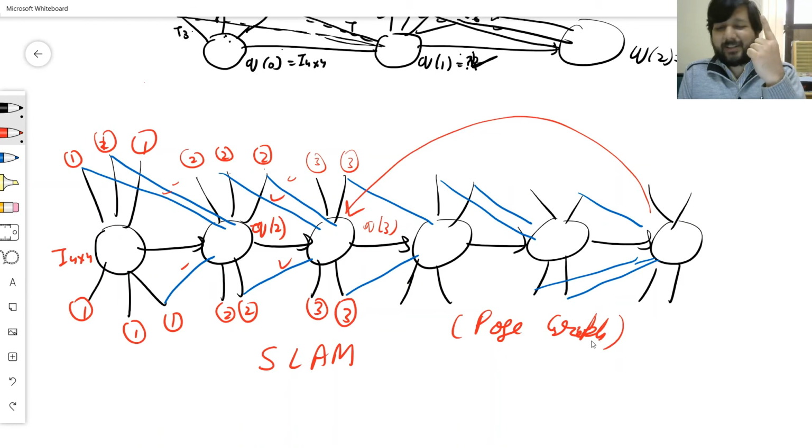It could have been solved at a global level pretty easily using my own variant of GPS, but then the motion models calculated errors by integrating signals, and the errors kept on increasing, and the observation models were problematic for the reason that the observation signal could also have noise. So usually you fuse both of them up. You fuse a motion model and an observation model by the tracking applications.